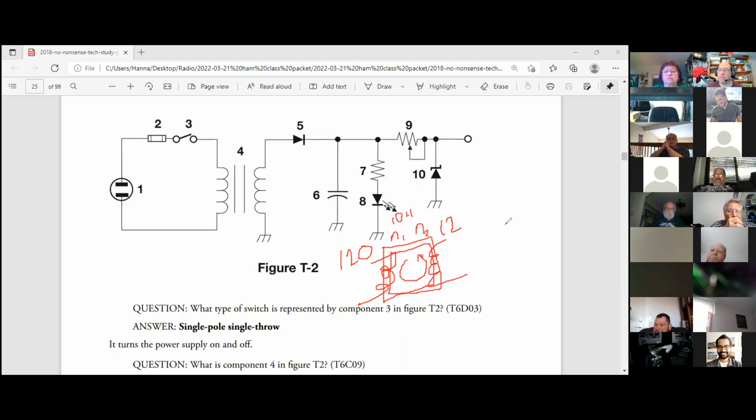And this is actually really important because what do we know about energy? It can't be destroyed. Neither created nor destroyed. So if I have a different voltage over here, what does that mean about my current? Because my power has to be basically the same. My current is going to be, let's say, 1 amp on this side, and I'll be able to make 10 amps on this side, because power is equal to volts times amps. So it allows me to change my voltage and change my current.